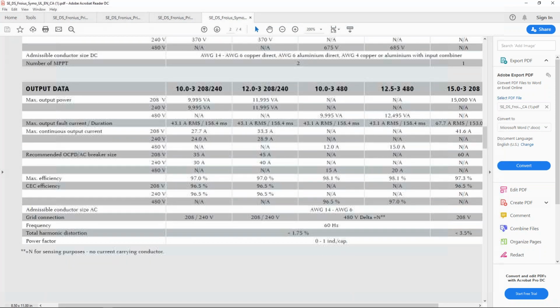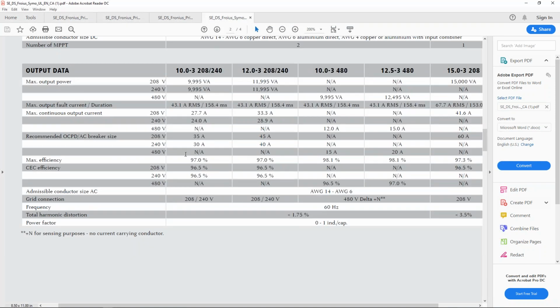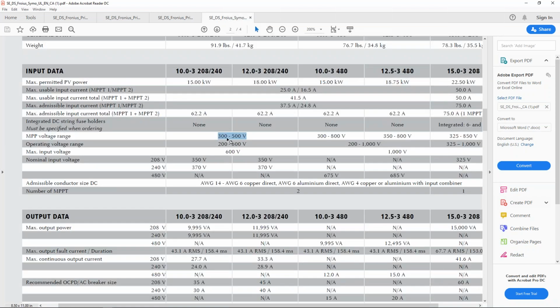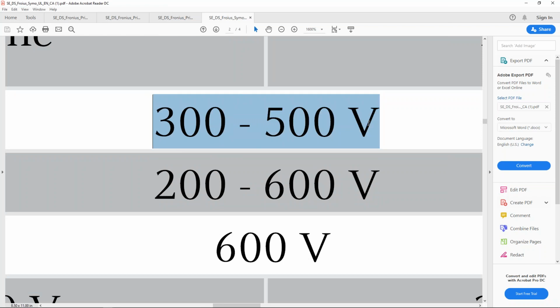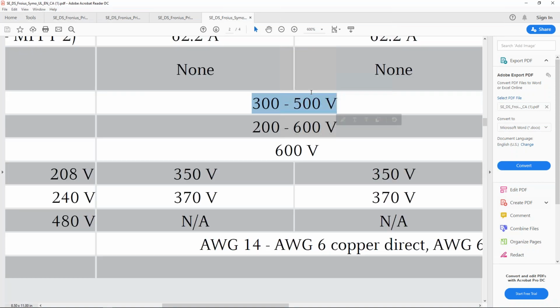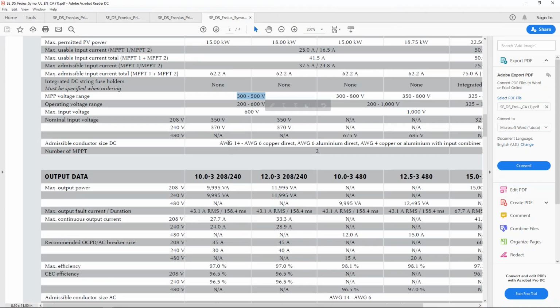Anything else that's interesting about this stuff? Output power. So what I'm trying to say is, in string inverter design, you would have to look at the voltages of your solar panels and say how many panels are on a circuit and multiply that by your short circuit voltage. Then you might have to look at the temperature coefficient of voltage and the minimum and maximum temperature of the array, and make sure that you stay within the operating parameters of the string inverter. That's what string sizing software does behind the scenes, which we talk about in other design classes.